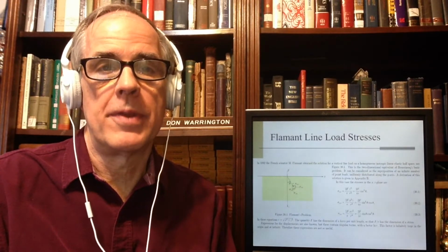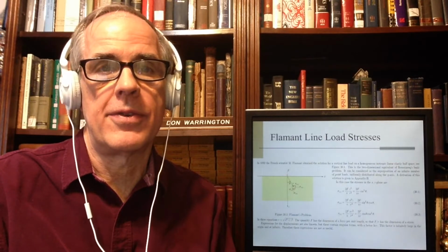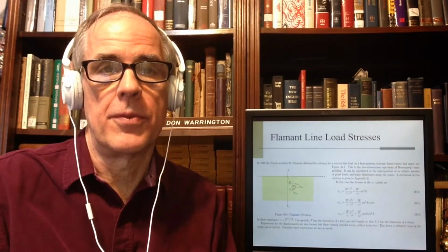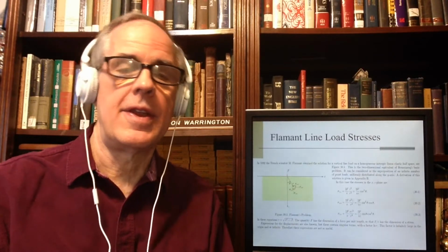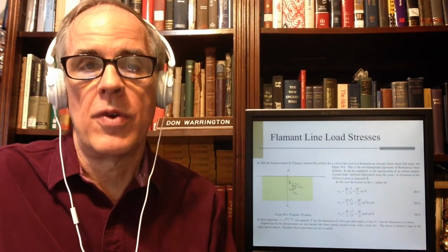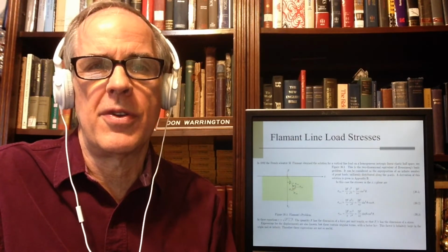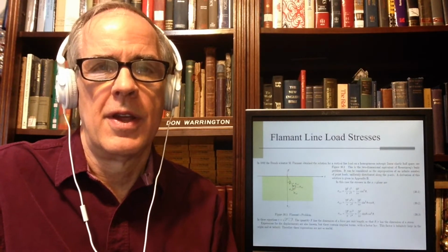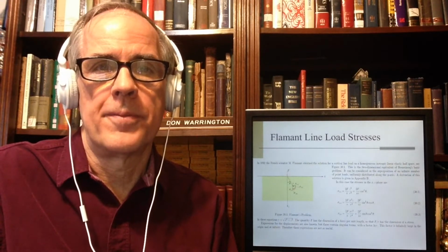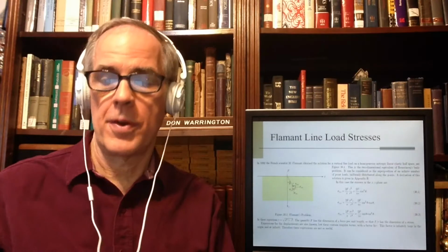The problem with line loads, as is the same problem you have with point loads. They have an infinitely narrow footprint, and as a result, you get a singularity at the load, which makes them of some utility for stresses and virtually none for deflections, as Voigt points out.